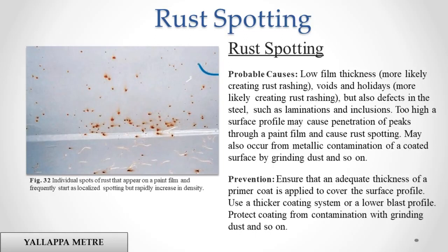Prevention: ensure that an adequate thickness of a primer coat is applied to cover the surface profile. Use a thicker coating system or a lower blast profile. Protect coating from contamination with grinding dust and so on.